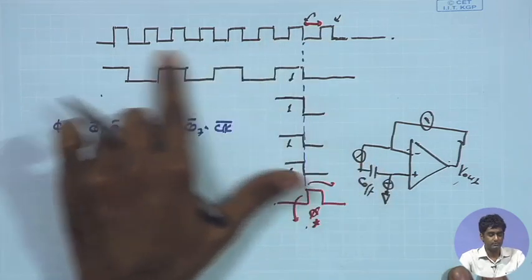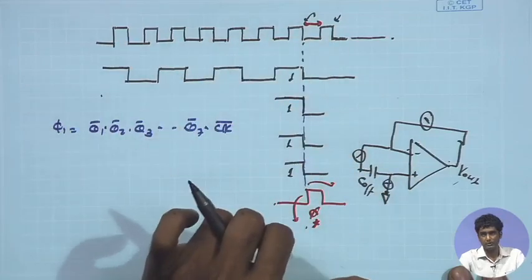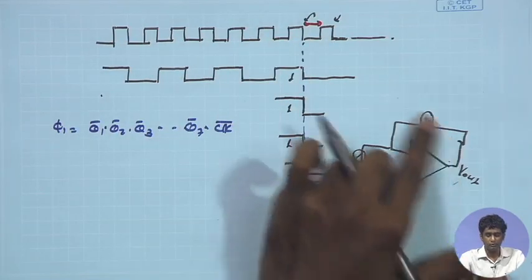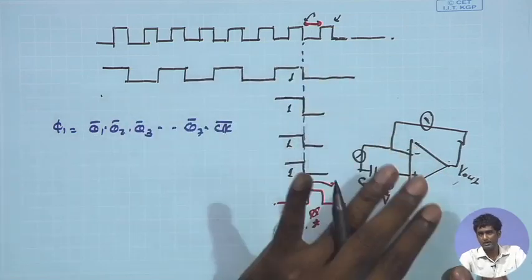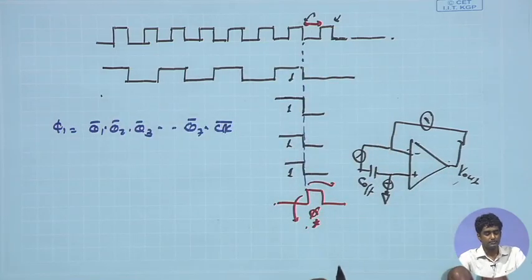So, that will be the constraint. So, if the frequency over here is 250 kilohertz, I would like the closed loop bandwidth to be several times higher than that, at least say a megahertz will be a comfortable number. So, that was the constraint.